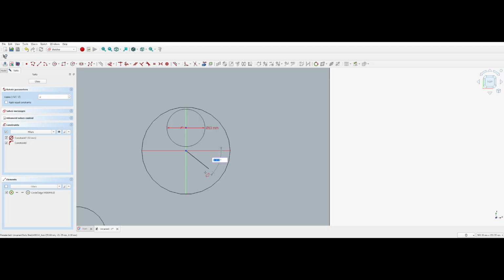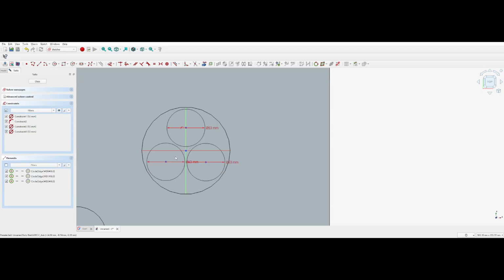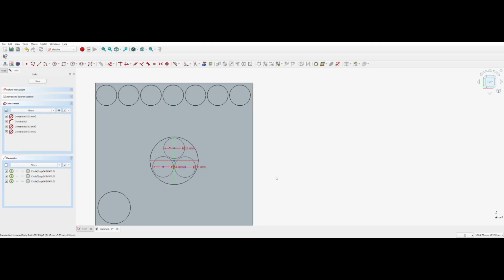We are going to select our middle rotation point to start, which I'm going to make the center of this. We are then going to select our end rotation point. I'm not sure exactly what it is. It'll select that, and we can slide out our circles. You can do the math on the degrees, or you can just fudge it a bit. And now we have a sketch with those 3.